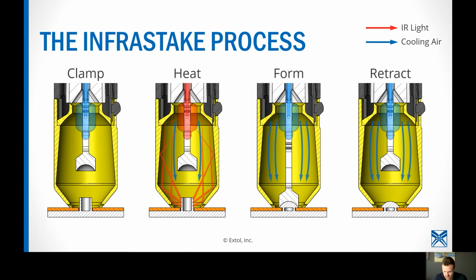There was a question that was asked a little bit earlier. AJ asked it, and I hesitated to answer it until we got to this slide. I'm not sure, maybe AJ, this answered your question, but the infrared process is heating the boss using the infrared light that's being focused onto the plastic. The punch is not heating the plastic and forming it in any way. Now it does draw some heat out.